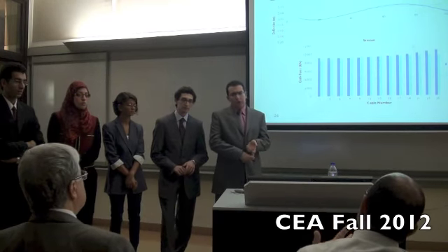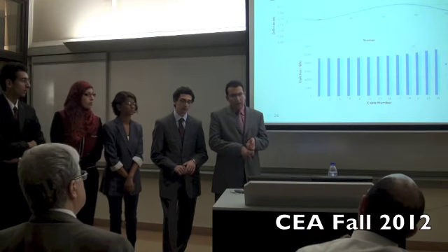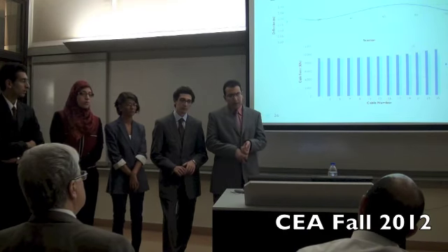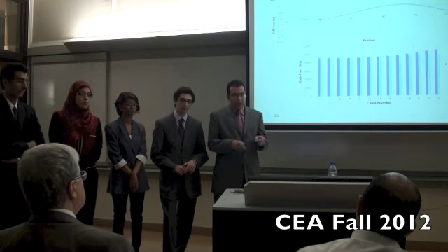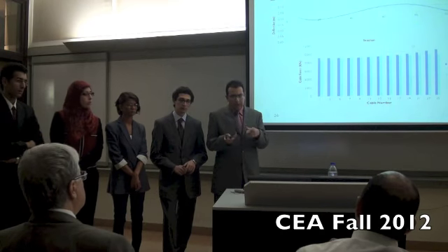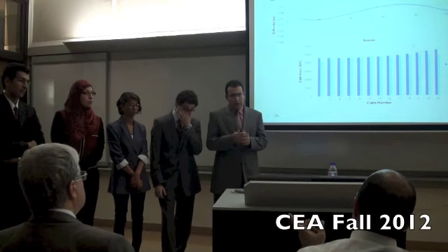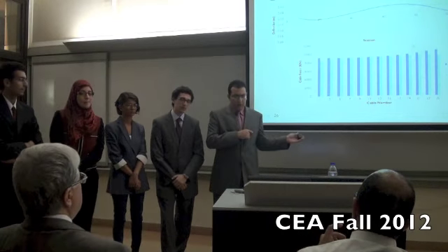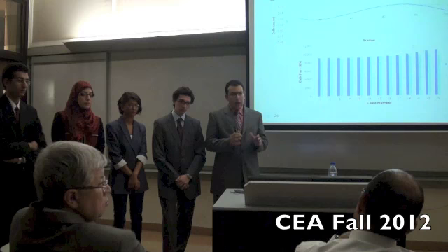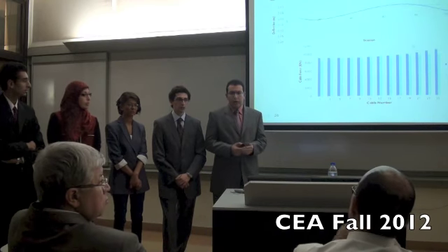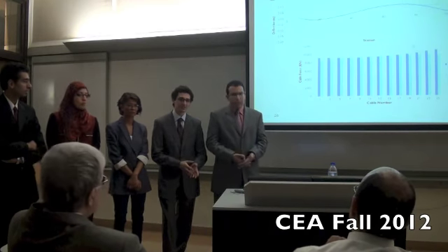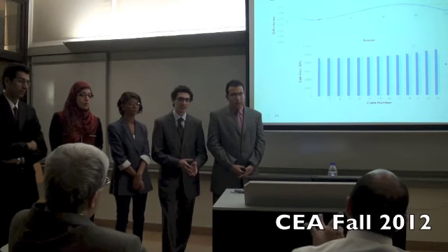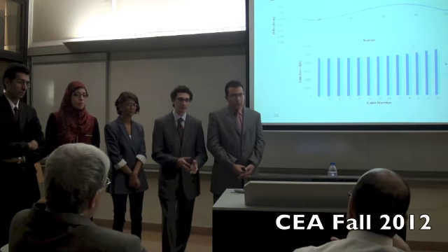The problem with area elements is that they magnify the negative moment and underestimate the positive moment. That's why we had to get out of that loop. And actually, at the end, we are going to run one area element model to verify our findings. So using the area model is not correct in the first place. It's about efficiency and saving time.